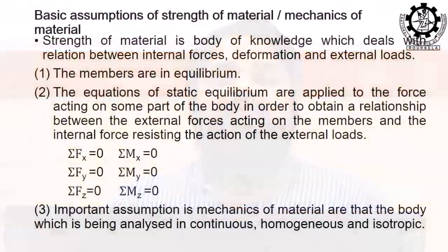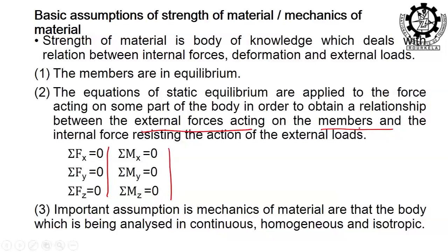The members are in equilibrium, and static equilibrium means all the forces and moments are equal to 0 in all directions. This is the major part of any static equilibrium condition. The static equilibrium conditions are applied to the forces acting on some part of the body in order to obtain the relationship between the external forces acting on the members and the internal forces. As I said, it takes both into consideration: the relationship between the external forces acting on the members and the internal forces resisting the action of the external loads, how they resist that force, because that is also very important in this case.